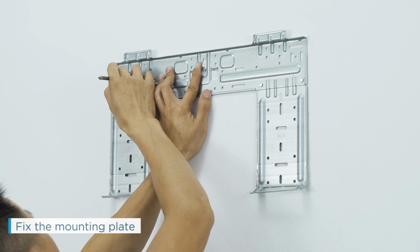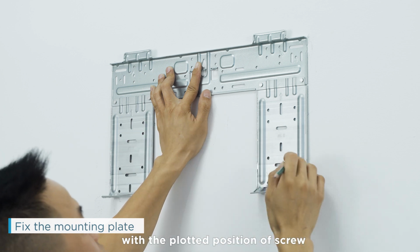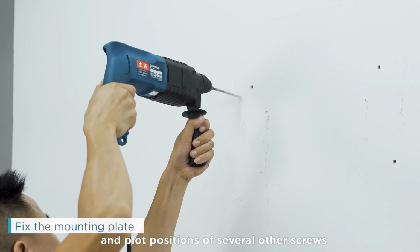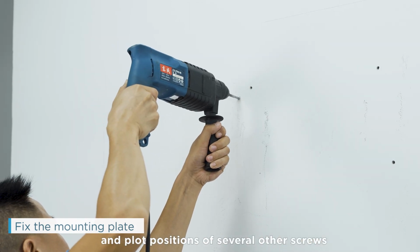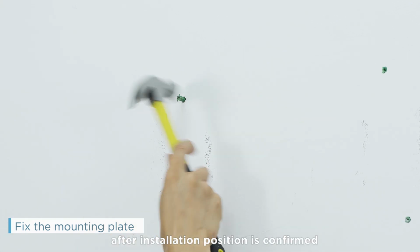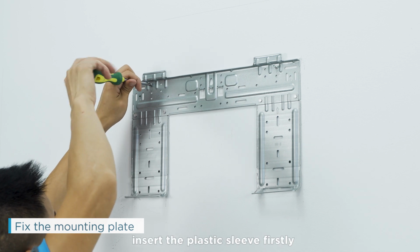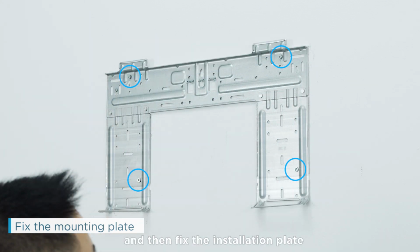Fix the mounting plate. Align screw hole corresponding to mounting plate with the plotted position of screw, and plot positions of several other screws. Fix and install the siding after installation position is confirmed. If it is a cement wall, insert the plastic sleeve first and then fix the installation plate with tapping screws.